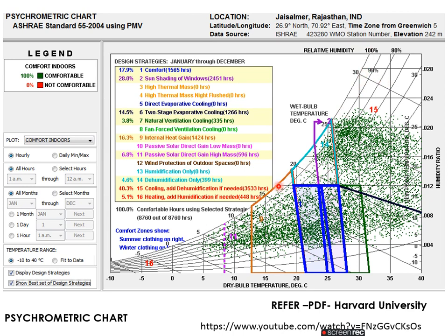So these curved lines are called the relative humidity lines, and there are slightly slanting lines which are called the wet bulb temperature. The lines projecting out from the x-axis are the dry bulb temperature, and the horizontal lines are the absolute humidity. So 100, 90, 80, and then 70, 60, 50, 40, 30, 20 and 10, which is very low.